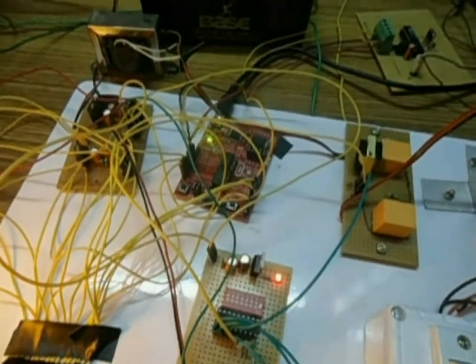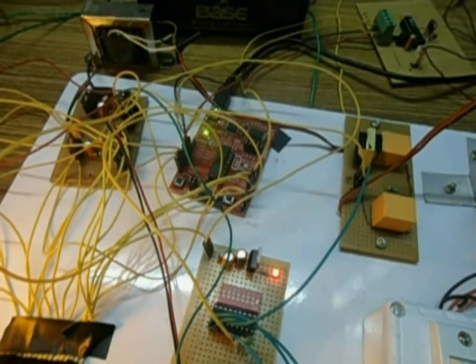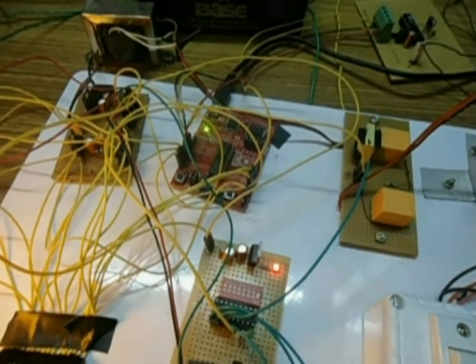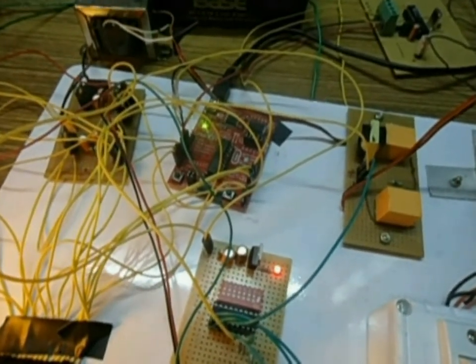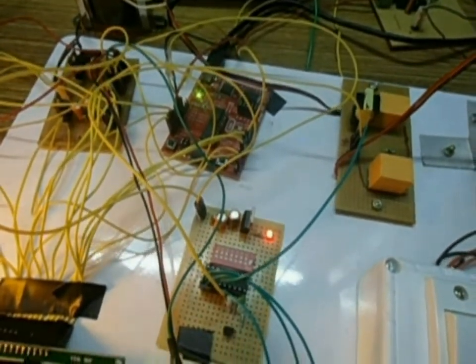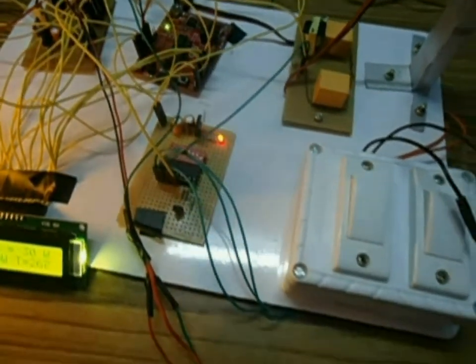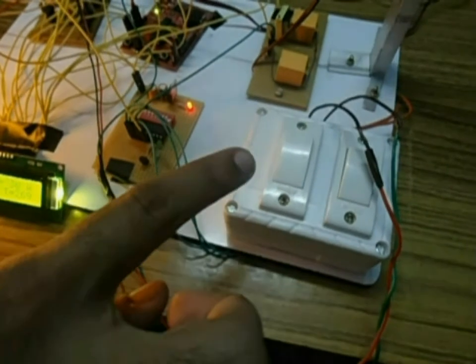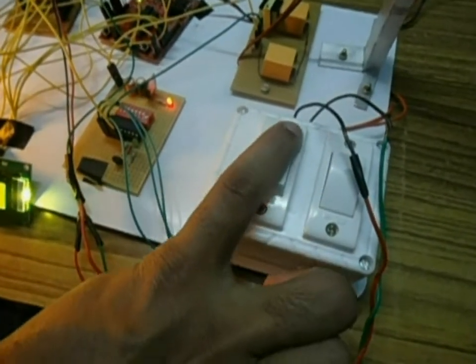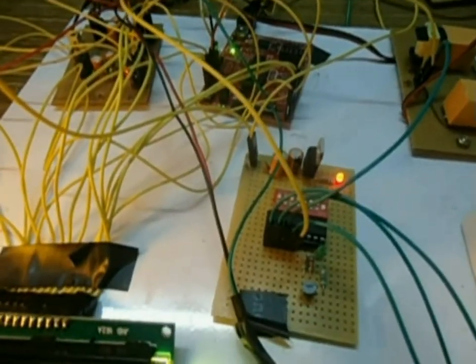The switching of the relay between the household and the transmission line can be automatic or manual. Most of the times it is automatic. It can be made manual when the occupants of the household are away from the house and the whole power can be fed to the transmission line using this switch. We have employed power line communication where the data about the power consumed, power sold and the time are sent over the power line to the substation for billing purpose.